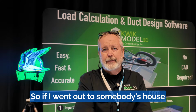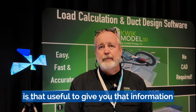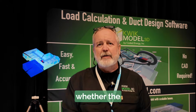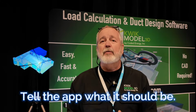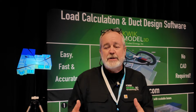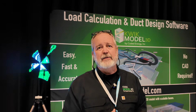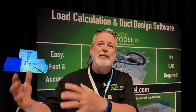So if I went out to somebody's house and I actually did static pressure testing or airflow testing, is that useful to give you that information as part of this design? Yeah, it tells us whether the ducts are sized properly. But if you're going to design the ducts, you want to tell it what it should be. You want to know what your system will run at, how much airflow at what static pressure. You plug that into the software. And basically that's what Manual D does: it says, I want a duct system that when I turn this air handler on, it's going to operate at this static pressure and give me this much airflow.